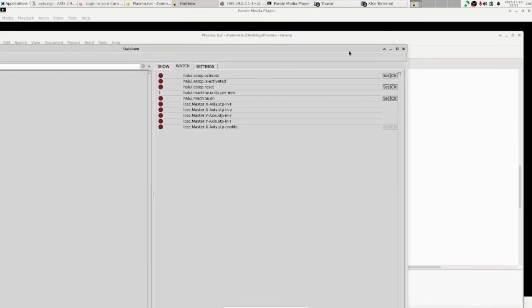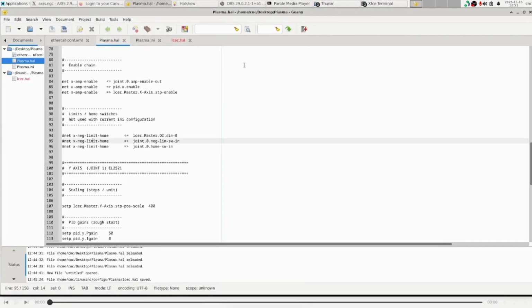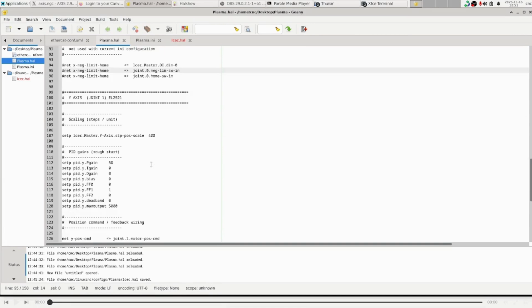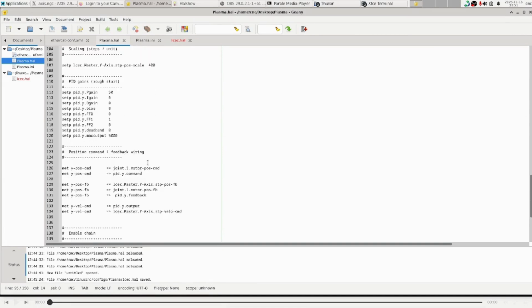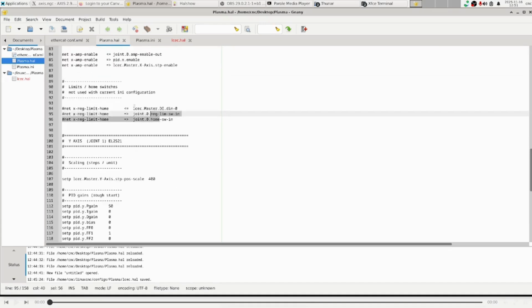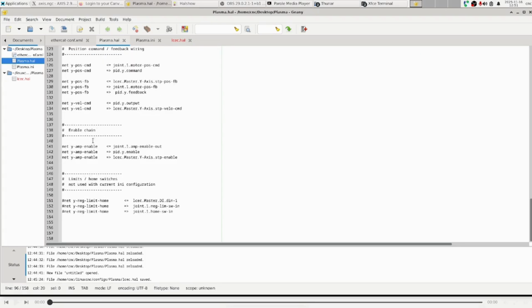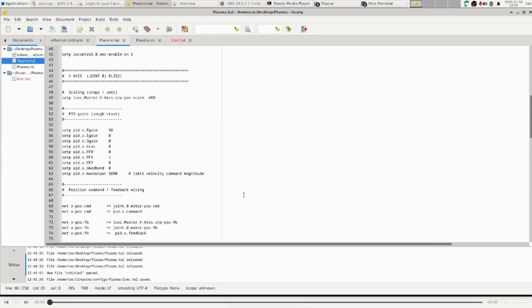Maybe I did something wrong with configuring, but I'm afraid of EMF anyway, so I don't really wanna kill my expensive step-gen cards, so I'm using normal digital input cards for the limit switches. I just have a negative limit switch, which will be the negative limit and the home of the machine, and I repeat that for X and Y, and that's basically all of it.